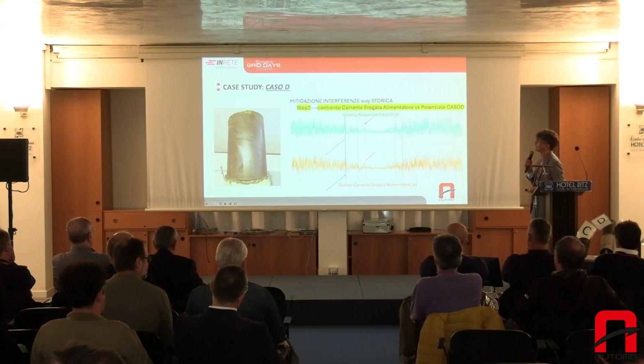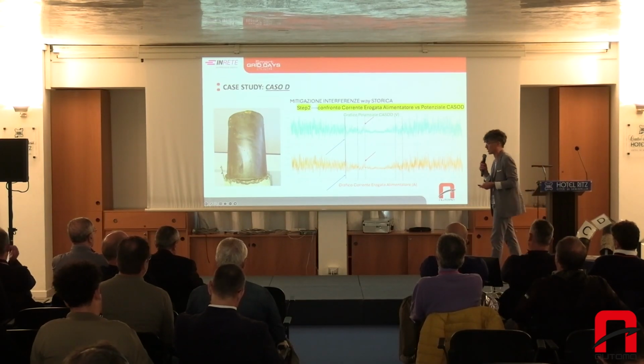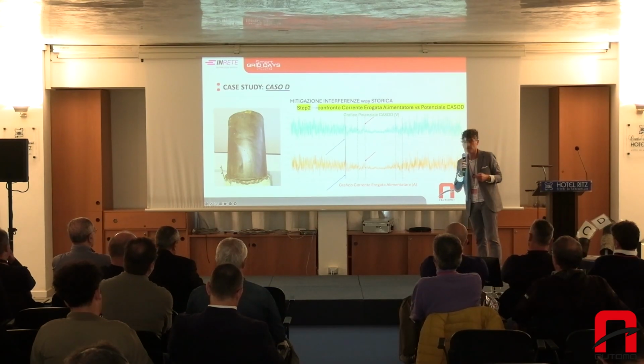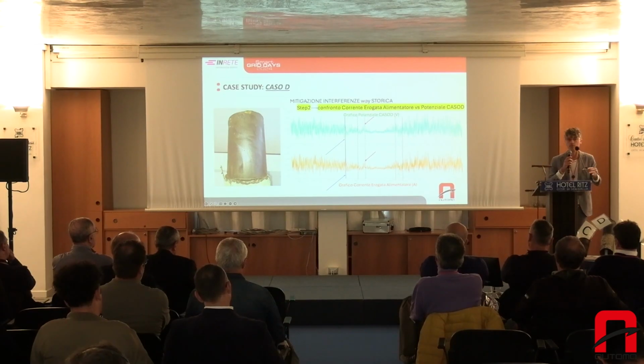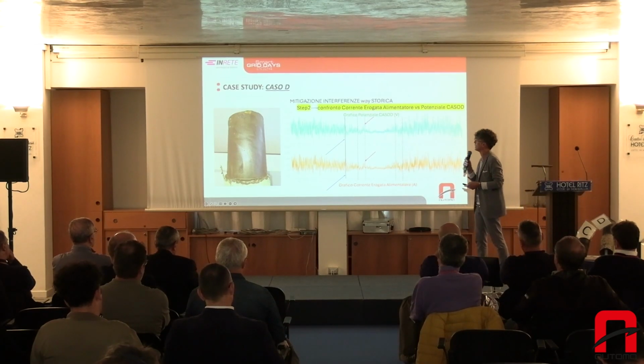The same when I'm in an anodic condition with the impressed current plant, where I provide more than 10 amperes. In this case, my anodic condition leads the potential to a more electropositive value. And all trends are the same, going in the same way. When I'm in an anodic condition in the power supply, I have an anodic condition also in the remote point.